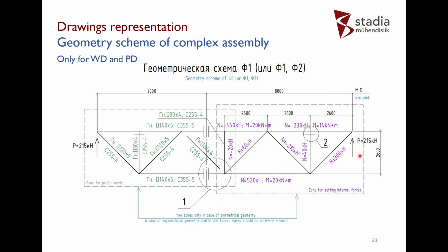These forces are needed also to design and check all details for punching, for welding, for everything. And these forces also are very important reactions, excuse me, because when a person starts to design this drawing, the joint detail, he must be able to do it without doing the calculation from the beginning.